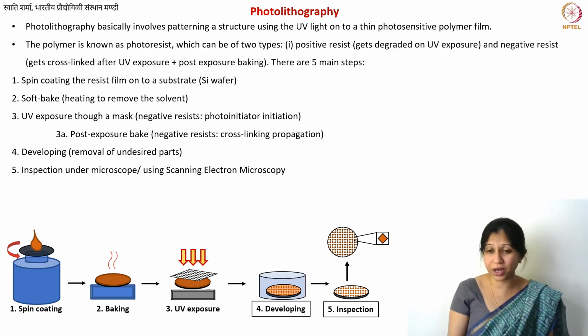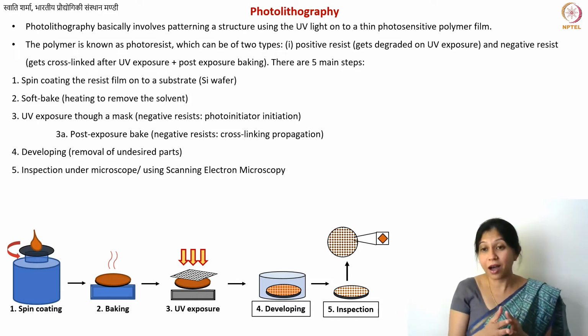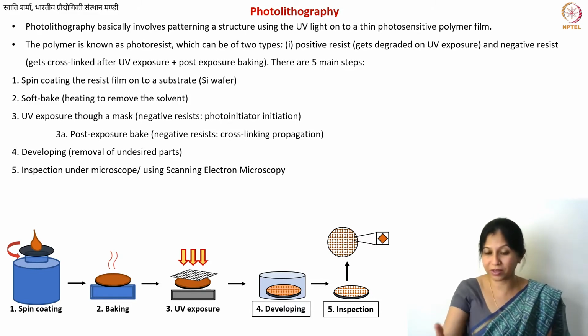In the case of SU8, we know it's a type of phenol formaldehyde resin because these resins are traditionally used for making glass-like carbon structures. All these larger structures also use these resins. So it was already expected that this will give a similar material at micro scale as well. And that is why this resist became very popular for yielding glass-like carbon.